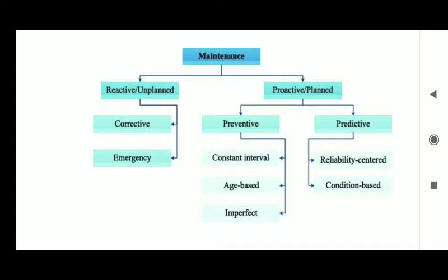I will give an example. For maintenance of a generator, they will tell you every 250 hours the generator needs to be serviced. Does it mean that we are going to service every 250 hours? Every 250 hours means when the generator is running. That is when it could be 1 month, it could be an interval of 2, it could be an interval of 3 months, depending on how you have PHCN supplying you power supply within that environment. But for a preventive, you've already created a standard of 250.